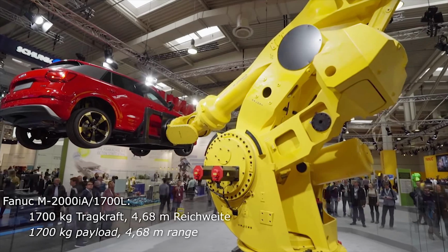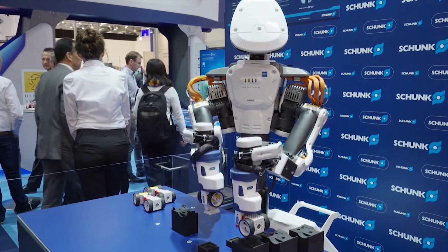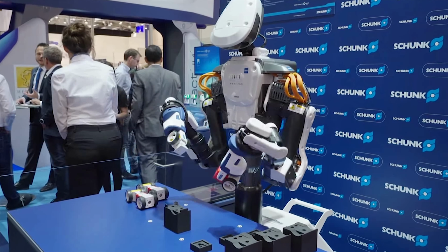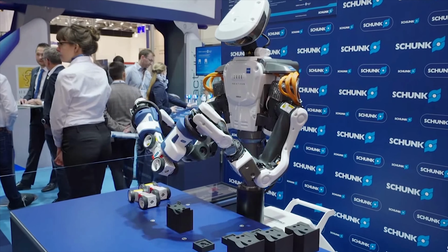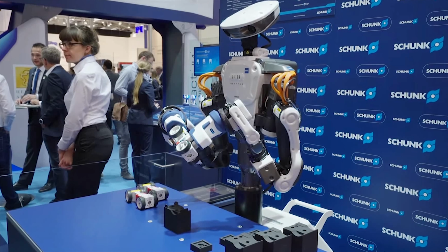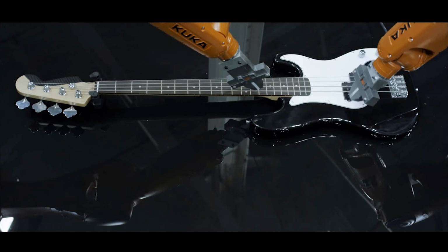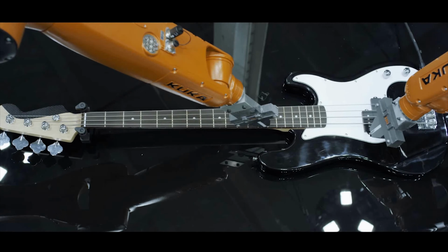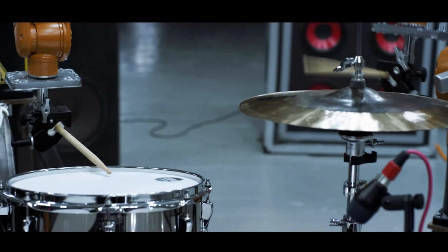A good example would be removing large stamped parts from a press and placing them in a rack or similar dunnage. In welding, a column boom manipulator is used to increase deposition rates, reduce human error and other costs in a manufacturing setting. Additionally, manipulator tooling gives the lift assist the ability to pitch, roll, or spin the part for appropriate placement. An example would be removing a part from a press in the horizontal and then pitching it up for vertical placement in a rack, or rolling a part over for exposing the back of the part.